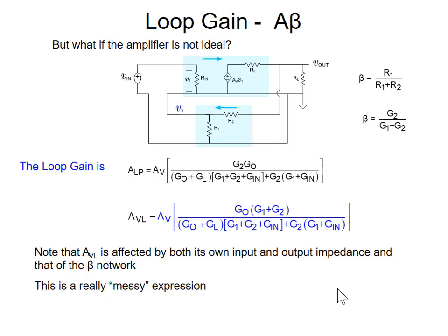And in fact, when we do calculations with loop gain, if we're going to use phase margin criteria, we like to assume that the A network is independent of the beta network. And then we put the 1 over beta line in for different values of beta. Now what do we find here? Not only do you have to know what beta is, you have to know how you realize the beta network to correctly get the AV, if you want to put the 1 over beta line in.